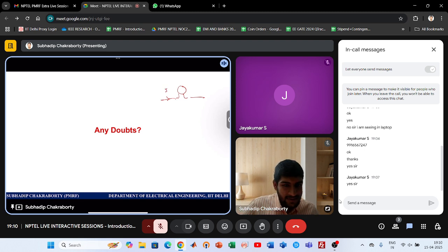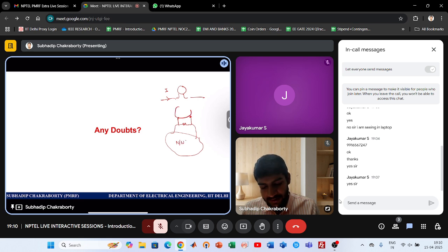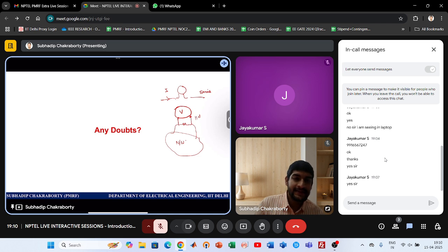The current is responsible for the torque, right? Which is obvious. But if you want to measure the voltage across two nodes of a network, let's say you have an element and you want to measure the voltage, you connect it in parallel. And if you want to measure the current, you connect it in series.